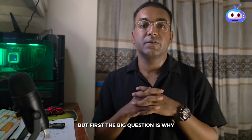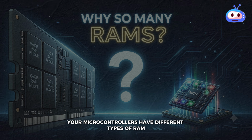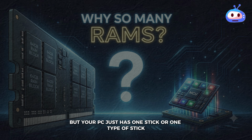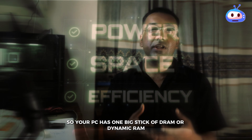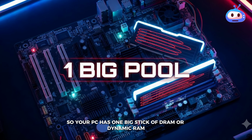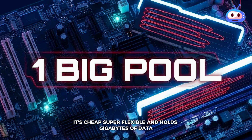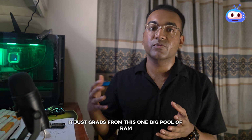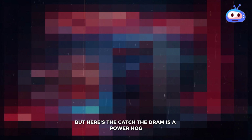But first, the big question is why do microcontrollers have different types of RAM, but your PC just has one type of stick? It all comes down to power, space and job duties. Your PC has one big stick of DRAM, or dynamic RAM. It's cheap, super flexible and holds gigabytes of data. If your Google Chrome or Safari needs a lot of memory, it just grabs from this one big pool of RAM. But here's the catch: the DRAM is a power hog.